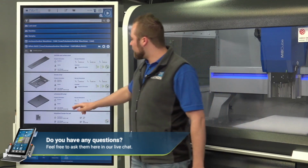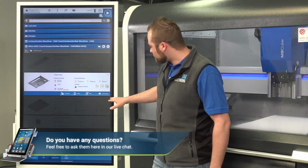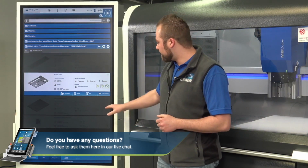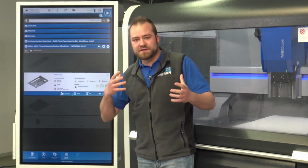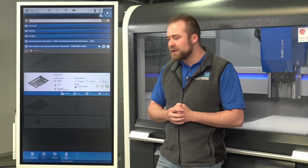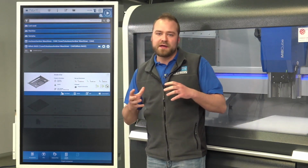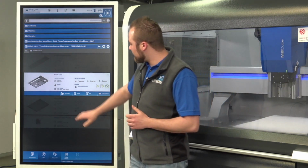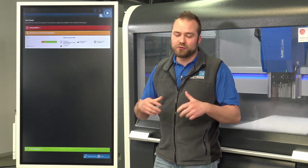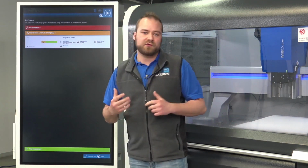You tap here on your program, and then you can also see some buttons on the right side, load program, so there you can load it. Then we have edit and delete, so if you have to change something in the program or delete it if it's wrong. The next step is to check your tools, and you can do this by tapping this button. Then you can see which tools you have programmed, which tools are inside the machine, and which one you still have to put inside the machine.